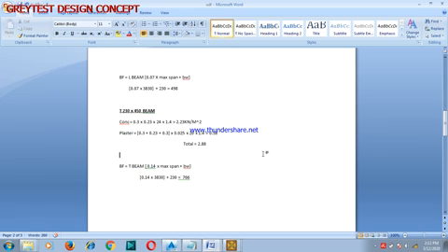Another thing you should take note of is when you are dealing with BF, the calculation for an L beam or T beam when it is continuous is different from when you are dealing with a T beam or an L beam that is simply supported. But in this particular video, I am not going to go deep into that, because I'm trying to make it as brief as possible. That is why I will advise you to get the Reinforced Concrete Design book by Victor Oyenoga, and the manual of RCD 2000.